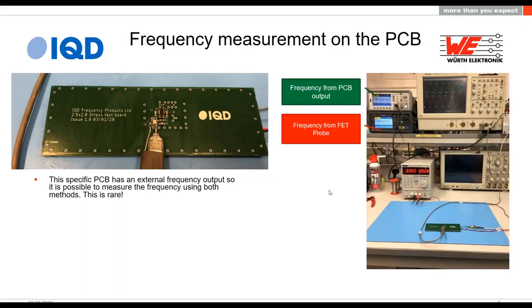Okay, but this PCB was the one that we made in order that we could measure the frequency without having to do that. So I'm really lucky because I can get the signal. And that's what our green trace is on the top there. We've got a square wave coming directly from that, which is lucky because that's what I made it for. As I said, I'm yet to see a customer's PCB that's got that function. If you did have a function on your PCB that gave you a frequency output, some mathematical derivative, maybe a multiple or a division, it'd be perfectly fine to use that, yeah? The only thing you need to be cautious of is